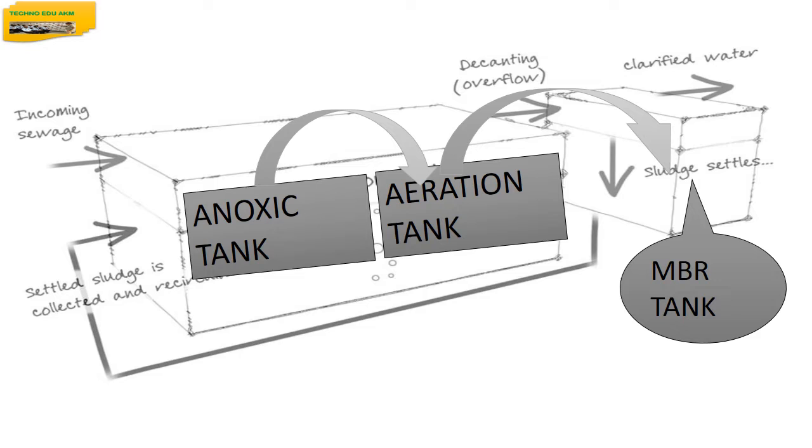In this concern, I would like to tell you a few guidelines for the operator. Start the raw water lifting pump first. Start the MBR feed pump and run it continuously for 24 hours. Maintain MLSS between 10K to 20K milligram per liter.